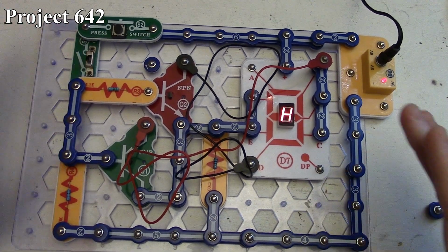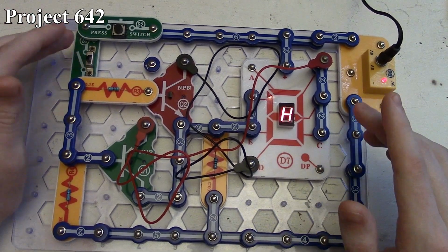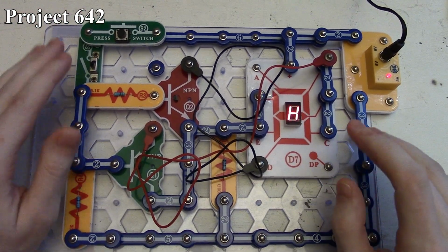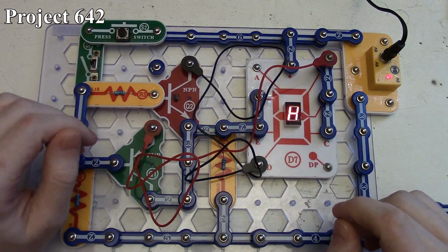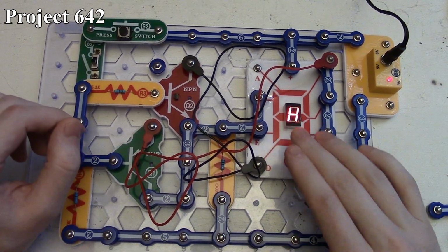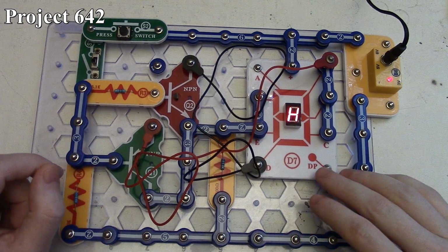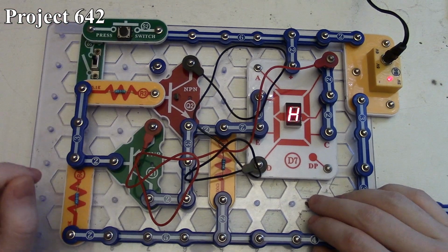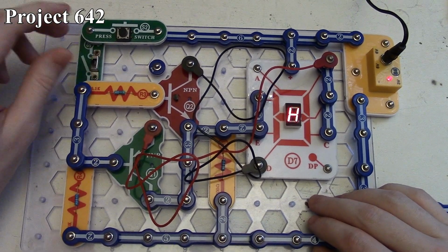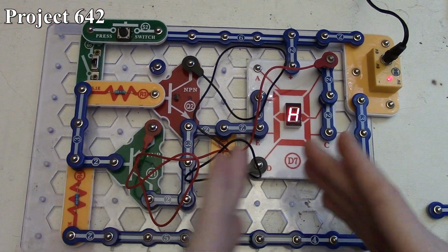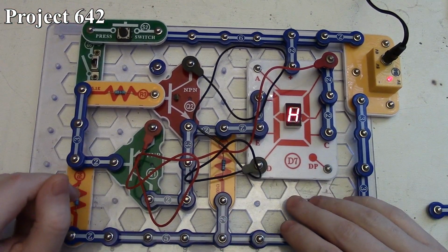Right now, the circuit is the same, but both our slide switch and our press switch are turned off, so they're both a false condition. But according to our 7-segment LED, we have a high or true condition on the output. Like a regular AND, if we only have one of these conditions true or turned on, the output condition is not going to change.